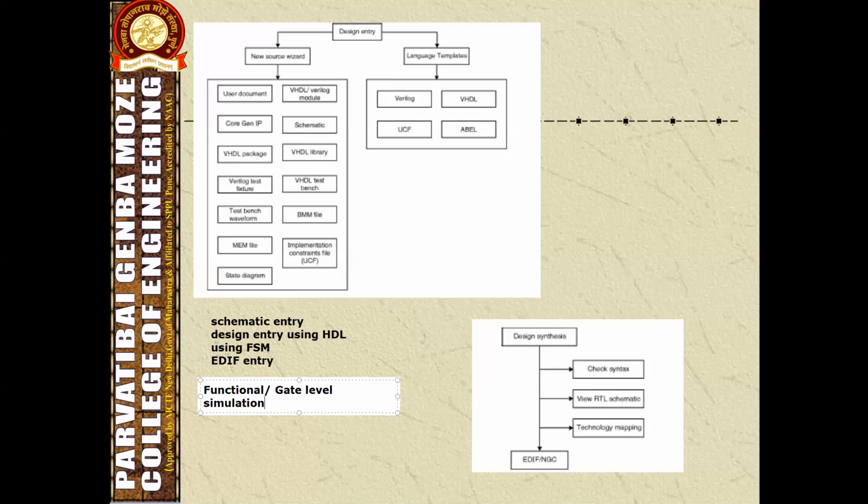The designs are tested by applying test inputs, and outputs are checked as per the specification. The important role of the simulations is to find errors in the design before the design is implemented in the target device. These simulations are mainly carried out at the initial stage of the system design.